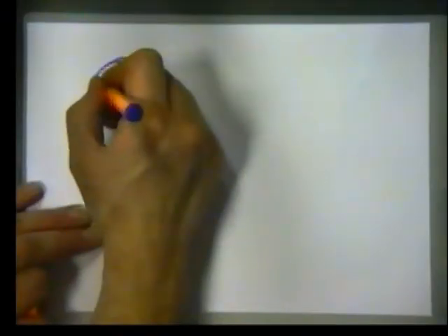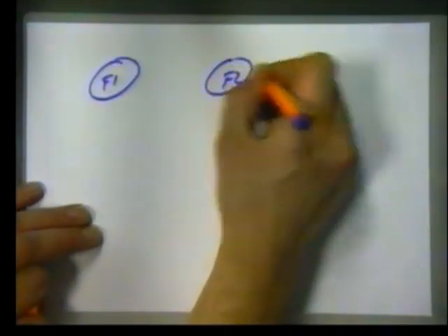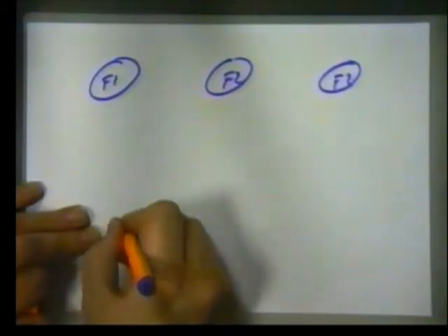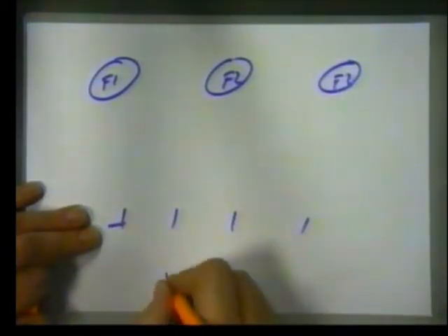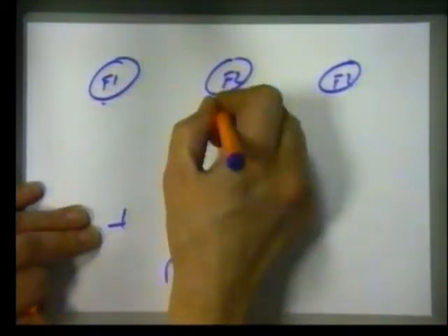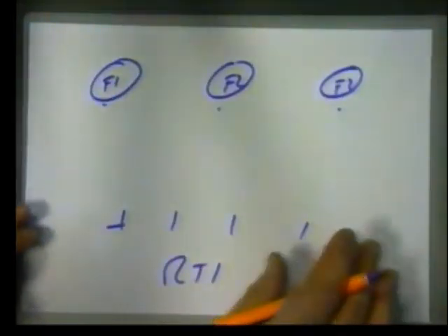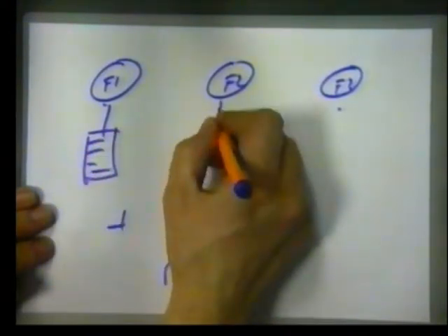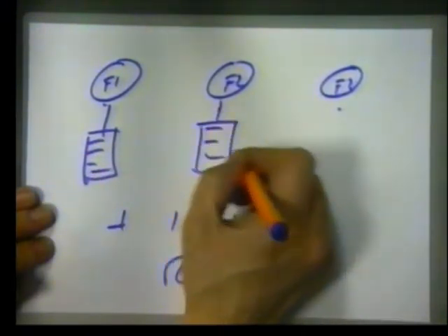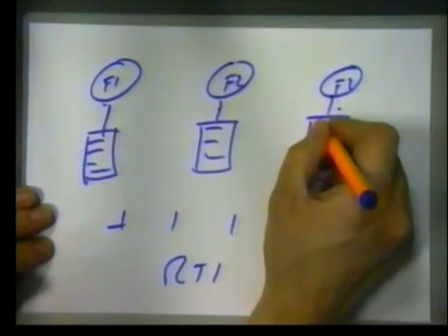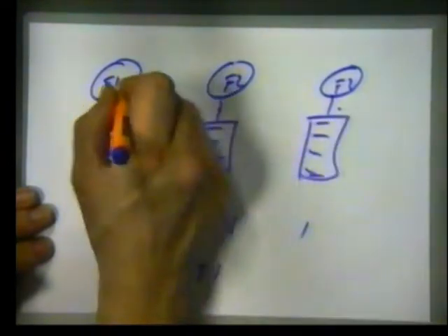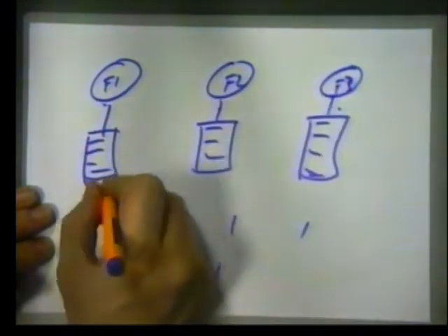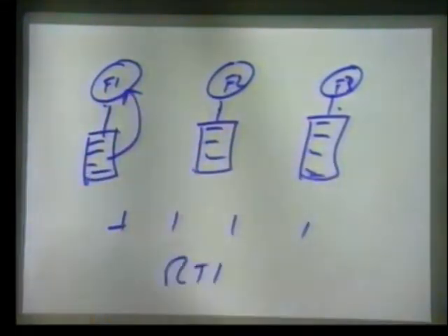These functions have no knowledge of each other. They're totally independent. But running in the background is this real-time interrupt that is switching them on and off in turn. And every time it suspends a task, it has to create a stack frame with the status of that processor in, so that when it is restarted, that information can be restored.